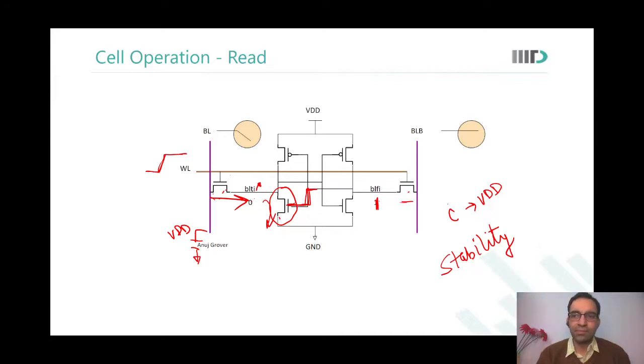There is no inverter in reality between them; we are just storing the value of bitline and bitline bar with the help of a capacitor. In reality, there was never an inverter directly between the bit lines. The inverter was on the data pin, and that went to the write driver. There was no inverter on the bit lines.